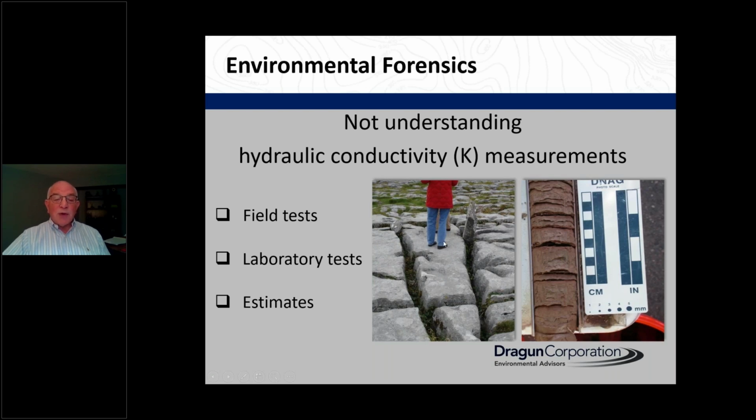Imagine if this fractured limestone was under 30 meters or 90 feet of soil. You would never know exactly where these fractures are, and you could drill 100 boreholes and not hit one of them. On the right, this is called varved clay. This is a glacial lake clay.